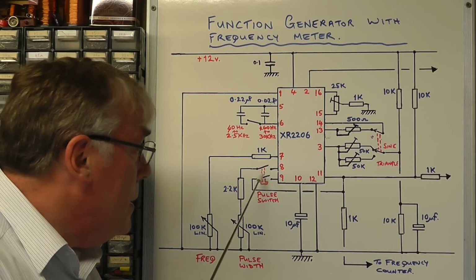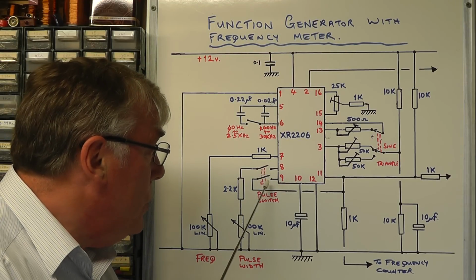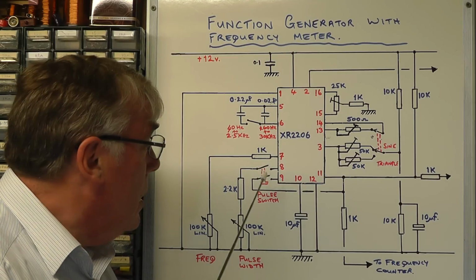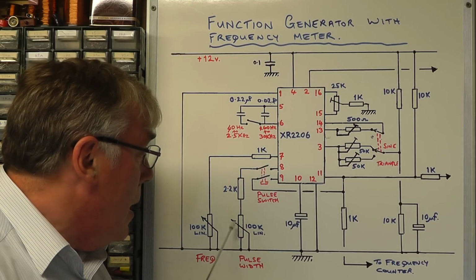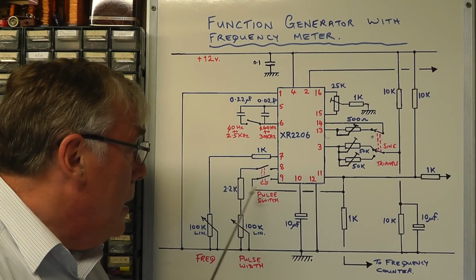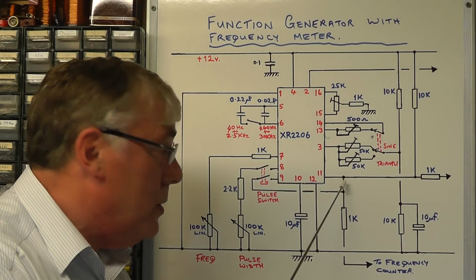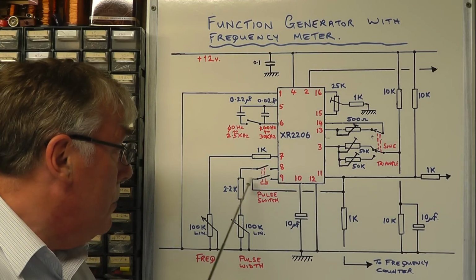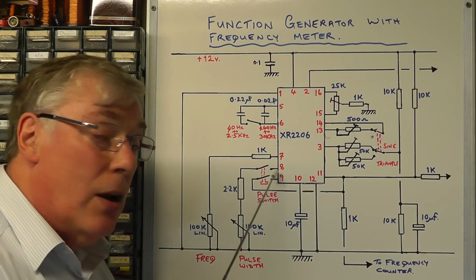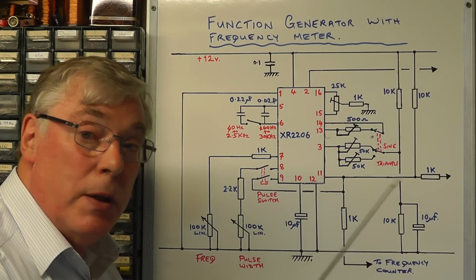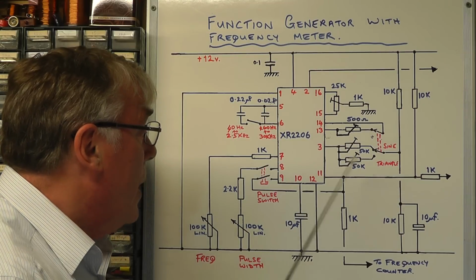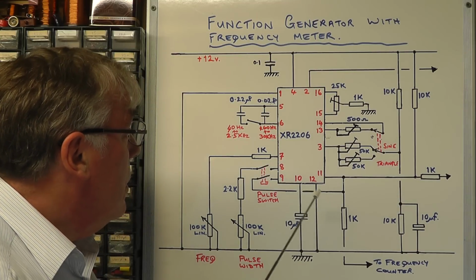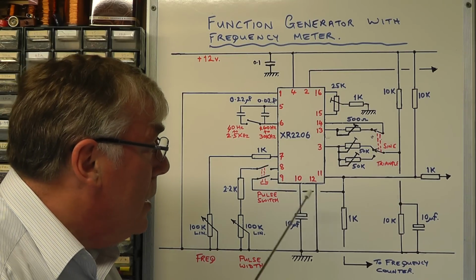So what you have here is a double pole switch. We throw that switch, it connects the additional timing resistor network in, and also connects pin 9 to pin 11. Now we have two timing resistor networks, and the signal going in on pin 9 is switching between the two, and that's creating the pulse out. So that's our basic circuit today.